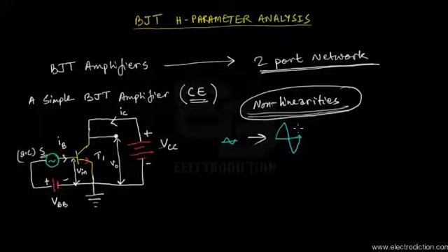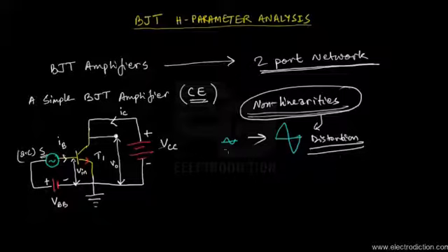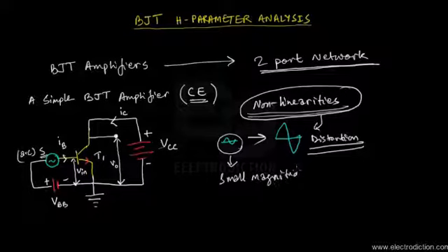And in many cases you see that your signal is going to suffer from distortion. This is going to create some distortion in your signal, so that the output signal is not exactly an amplified copy of the input. So whatever is followed conventionally is that the input signals are always kept at small magnitudes. So the BJT can take only small valued, or more precisely small magnitude AC signals as input, otherwise the nonlinearity is going to creep in more.